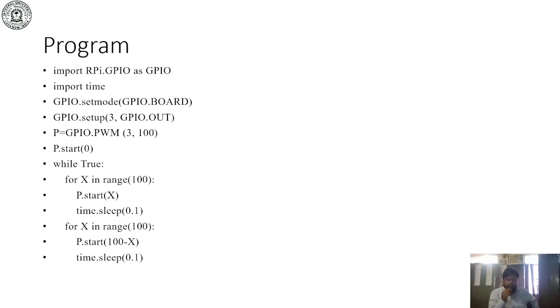In the third line, GPIO.setmode(GPIO.BOARD). As I already told you, we can use the GPIO pins as board pins or BCM.